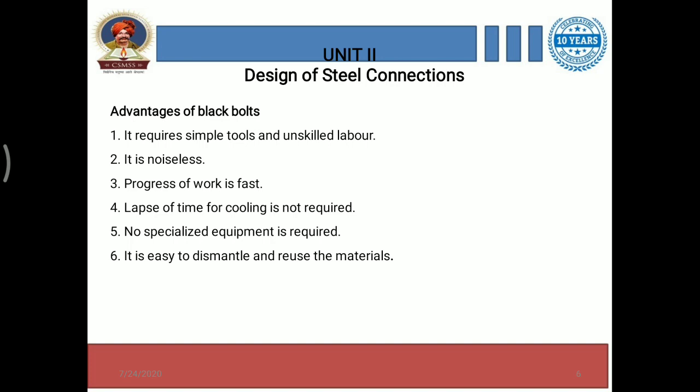Okay, the progress of work using bolted connections is always fast as compared to other methods, because you don't require that much time to fit a nut and bolt as compared to riveted or welding connections. Lapse of time for cooling is not required.